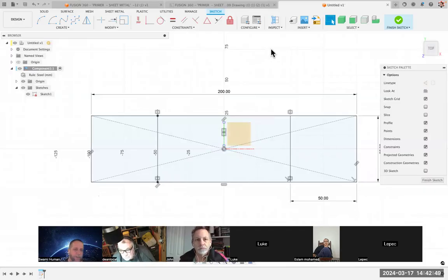And we are going to go back to our tree and hide our coordinate system. We don't need that anymore. That was just temporary. We are done, and it's fully constrained, by the way, with the little red lock. When you're working, you have an edit pencil. So in addition to these lines changing color to indicate that they're getting locked down, when everything is fully constrained, which is in general a good thing, you get a red lock to let us know that it's done.